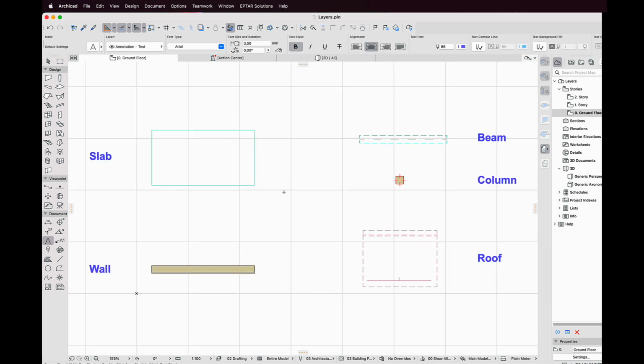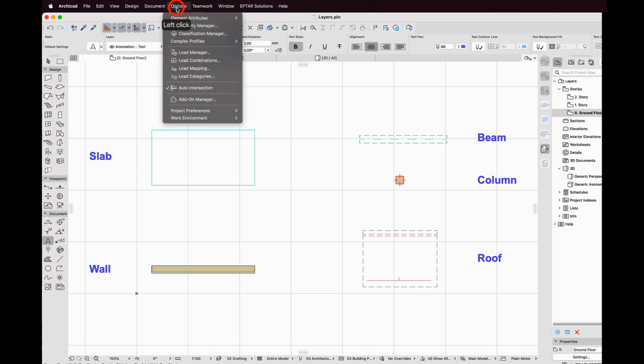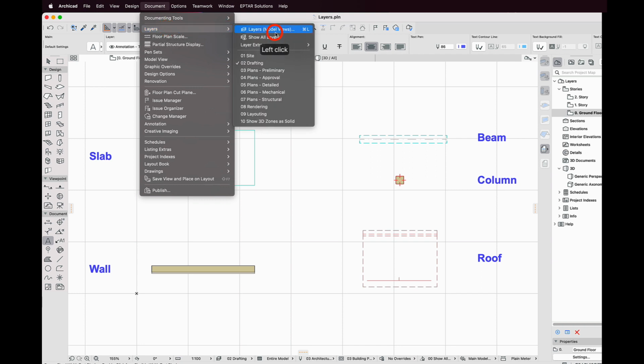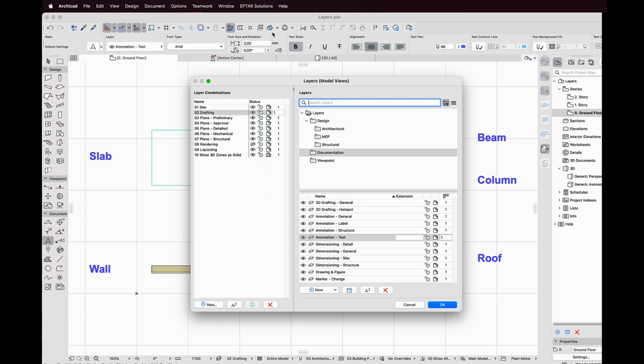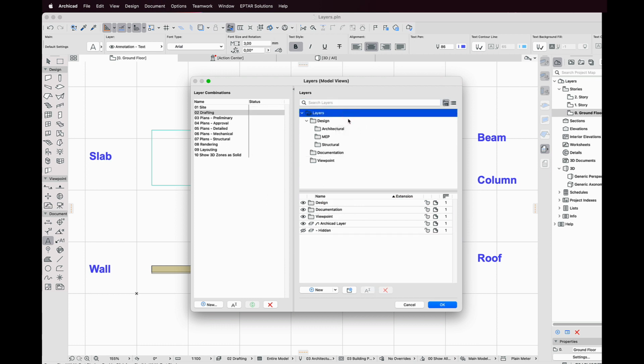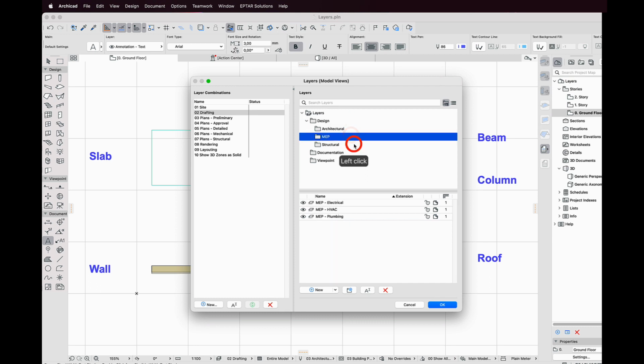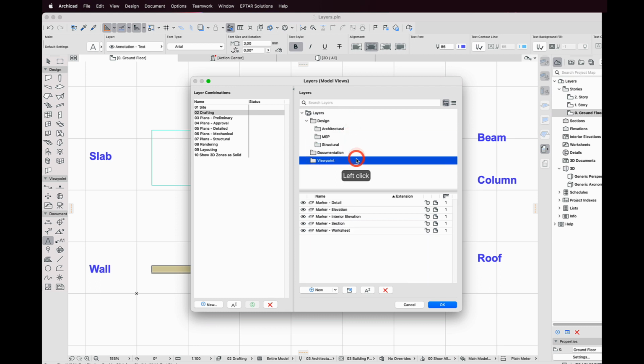New dedicated layers in Reinforcement 5.0. Up until now, when you place the reinforcement into the building elements, you could place them on Archicad default layers, or you had to create a new one manually. This has now been changed, and when you place a reinforcement, a new dedicated layer appears and the element will be placed on it. There is a default layer structure.